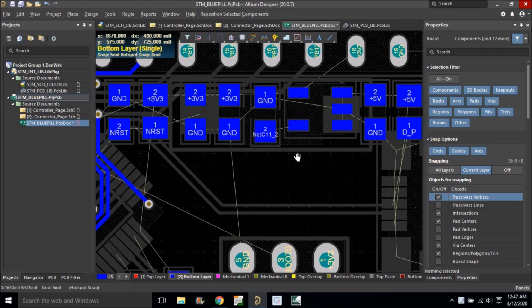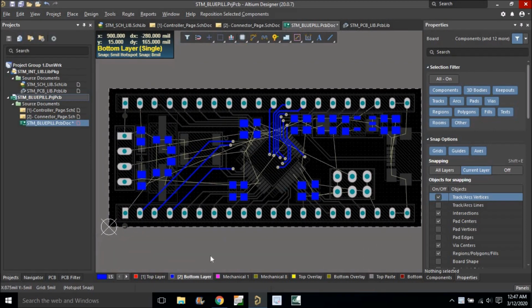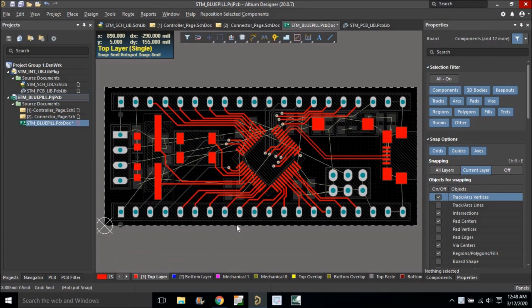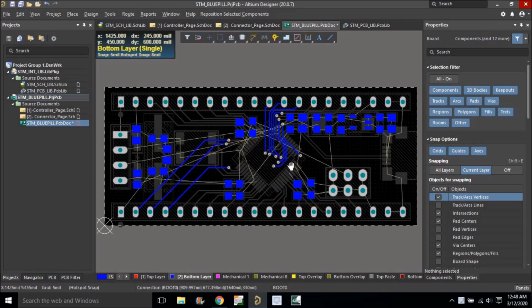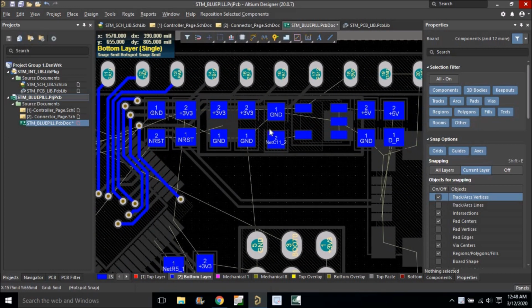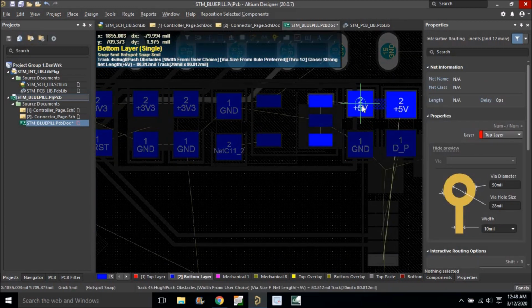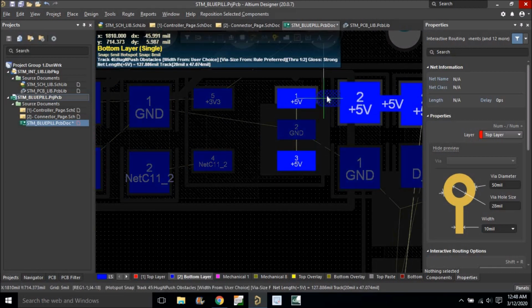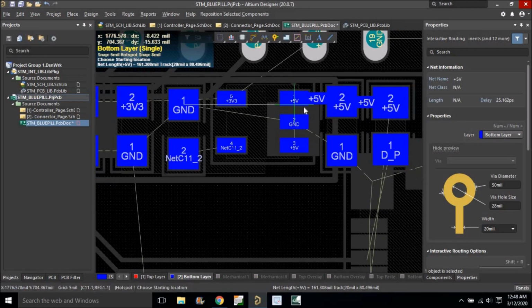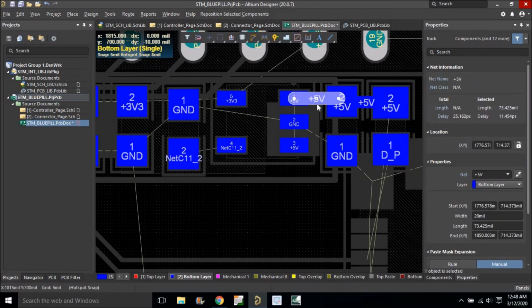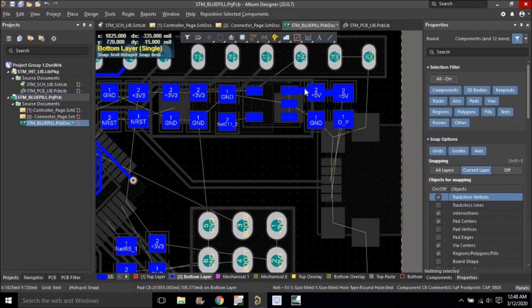So this will be easier, like you can watch only one layer. If I select the top layer, I'll see whatever is on the top layer only, right? So go to the bottom layer using Shift S and select the wire, connect it. So here I'm making this wire a little bit thicker, as I told you guys.